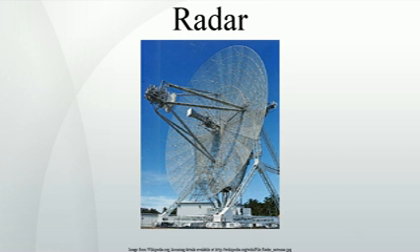One serious limitation with this type of solution is that the broadcast is sent out in all directions, so the amount of energy in the direction being examined is a small part of that transmitted. To get a reasonable amount of power on the target, the transmitting aerial should also be directional.